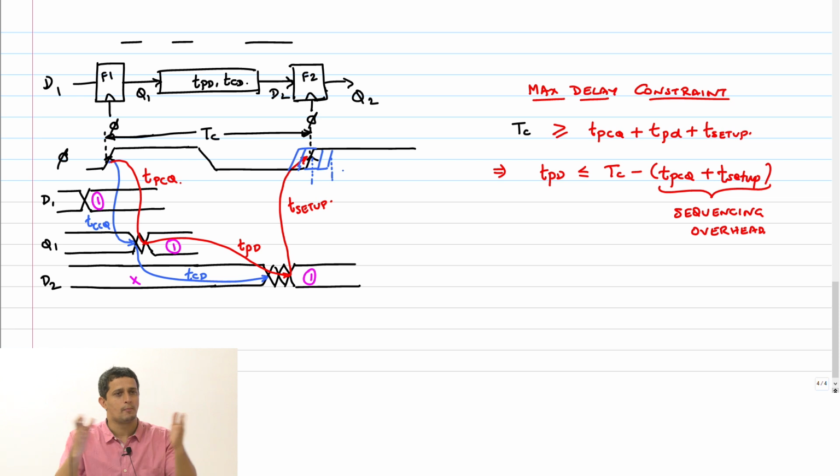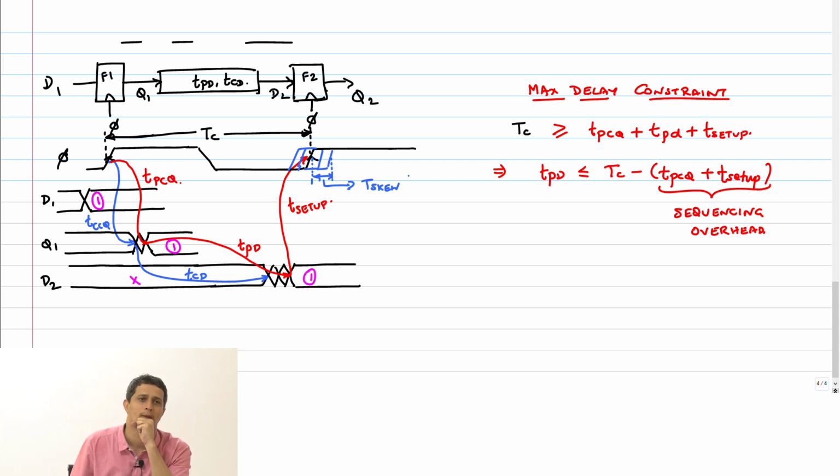So for example, I have shown you a band of curves here, right? A family of curves. Clock skew is basically the worst case delay. What is the worst case offset that I can have? That is called clock skew, T skew. Okay. Now I want to alter my timing constraint so that I am able to incorporate this skew as well.